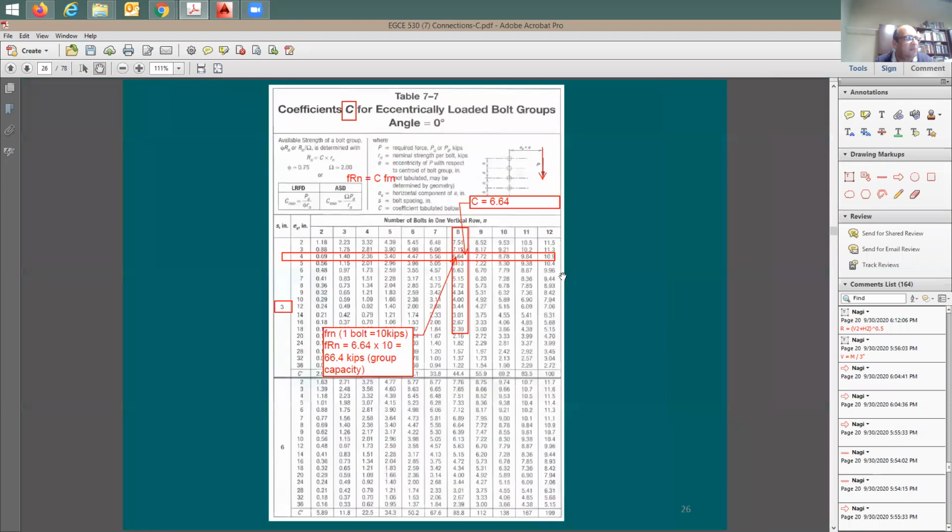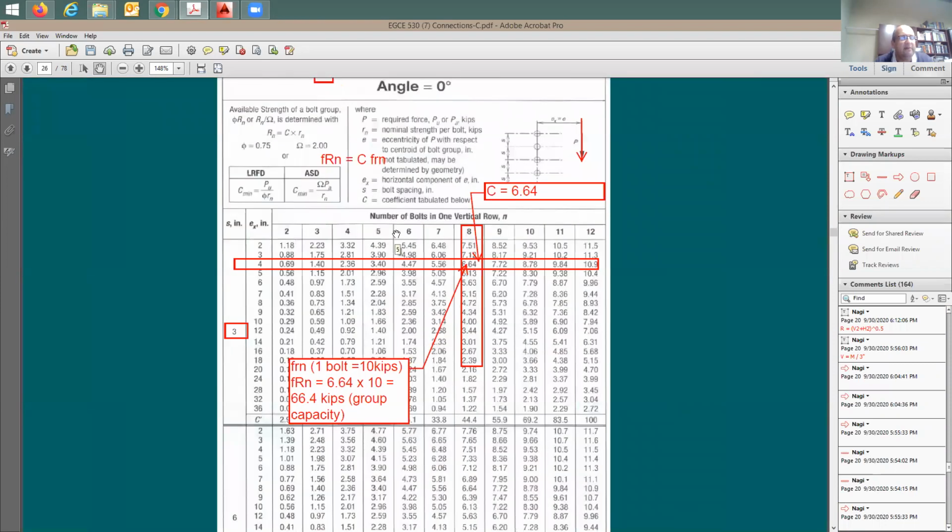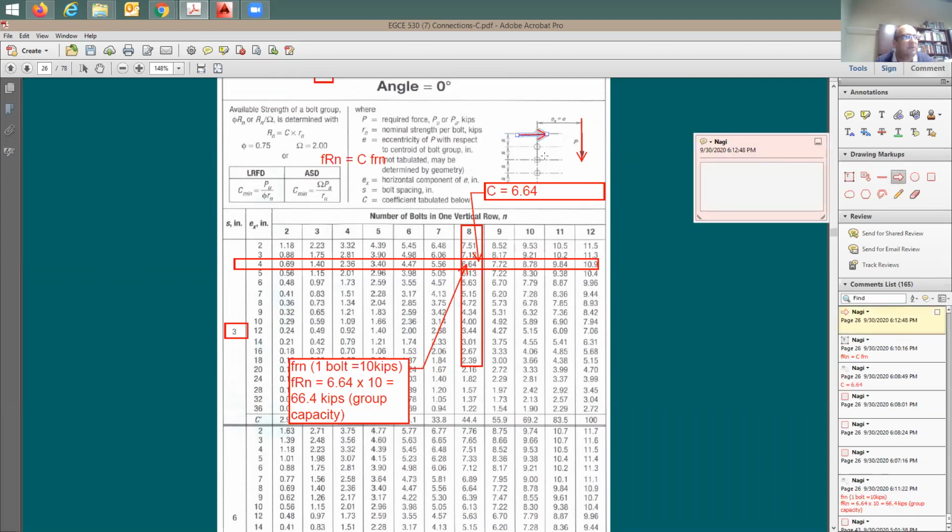Now let me jump here to my table. I didn't do it that way. What I have done, I have taken the total strength of the entire system here. Now I don't see any horizontal forces. But what happened, the equivalent number of bolts has been reduced, which means inherently, all the effect of this little force is coming this way, and another smaller force coming this way.